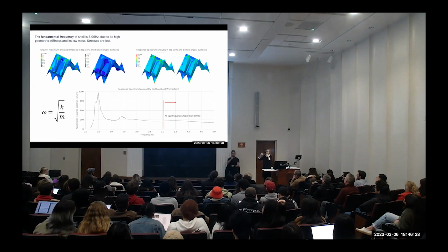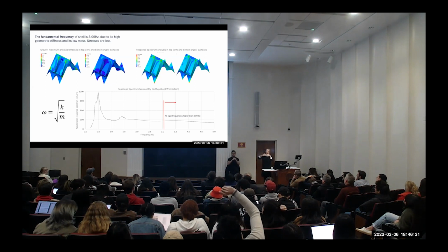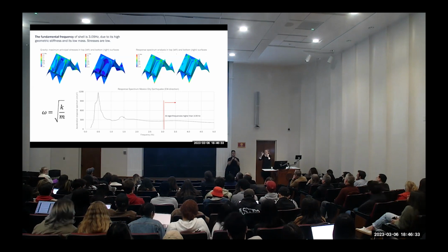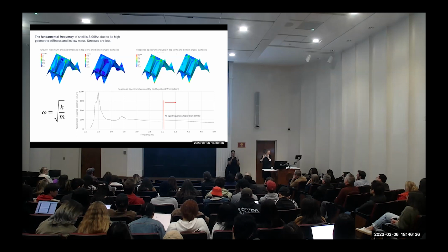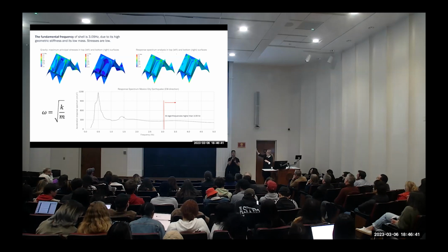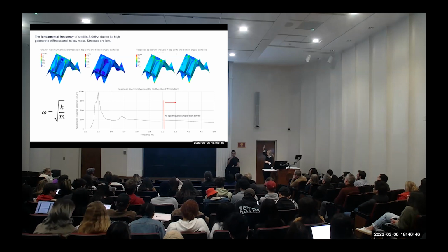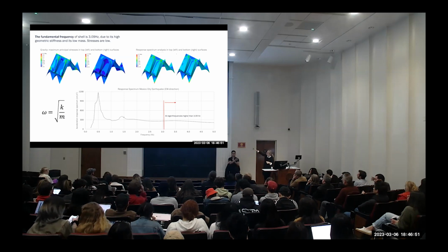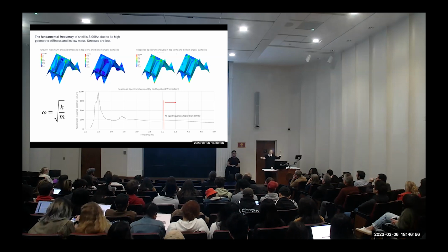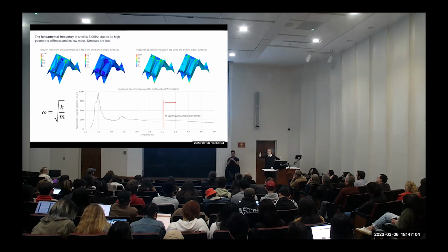The eigenfrequency of the structure is the frequency at which a structure likes to start shaking about. And what we found for the shell is that the eigenfrequency is very high. The value is 3.09 hertz or higher, because there's more than one eigenfrequency. And the frequency of the earthquake is much lower. It's more in the order of 0.5. The frequency of the earthquake means how often it hits in a certain time period, and the eigenfrequency of the structure are very far remote from each other.